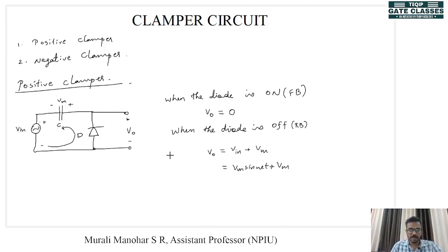So during the first half cycle, this happens. Initially the diode is turned on, and the capacitor is charged. When the capacitor is charged to Vm, the diode is turned off. Now we are going to look at the circuit when all this process has been completed. That is, the capacitor is already charged to Vm and that particular full cycle has been completed.